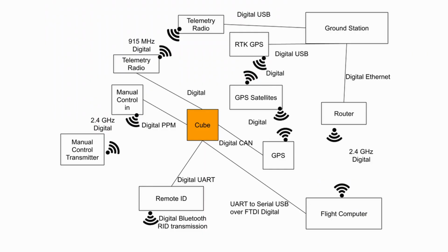To monitor and test the communications of the drone, we've tested both the range and the packet loss and throughput of the drone and all the communication that goes on it. For the range of the drone, we are testing it by observing the telemetry of the drone as we drive further and further away with the drone from our receiver. And to observe the packet loss and throughput, we've monitored that throughout doing our partial and full mission tests and just observe the data while we do those tests to see the packets as we perform different actions with the drone. You can see the results of these communication tests here. Here you can see a diagram of our communication system.